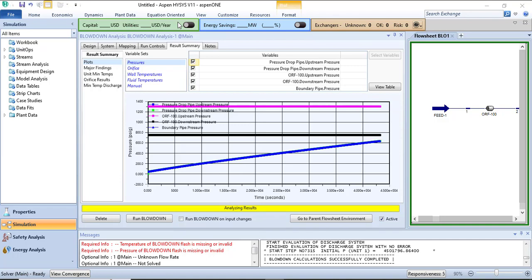So guys, the results are being analyzed by HYSYS. You can see that whatever time frame we have given, it is 12 hours, and at this flow rate we only reach up to 600 something pressure. So we have two options: either increase the time to about 24 hours or 18 hours, to get the pressure up to 90 bar G, that is around 1300 psi, or increase the flow rate. So there's a trial and error method in this pipeline pressurization to achieve the results.